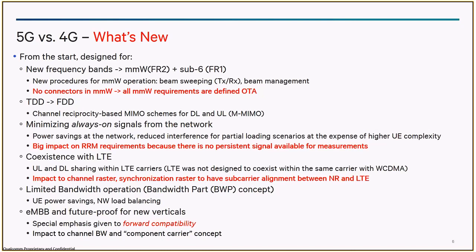But in 5G, you have this wide bandwidth where you can logically split this bandwidth into multiple chunks and ask a set of mobiles only to monitor this, right? And that is how you are probably able to accommodate more UEs. I think they're trying to simulate the FDD concept in TDD networks. This can be even done on FDD where your uplink is on a different band.